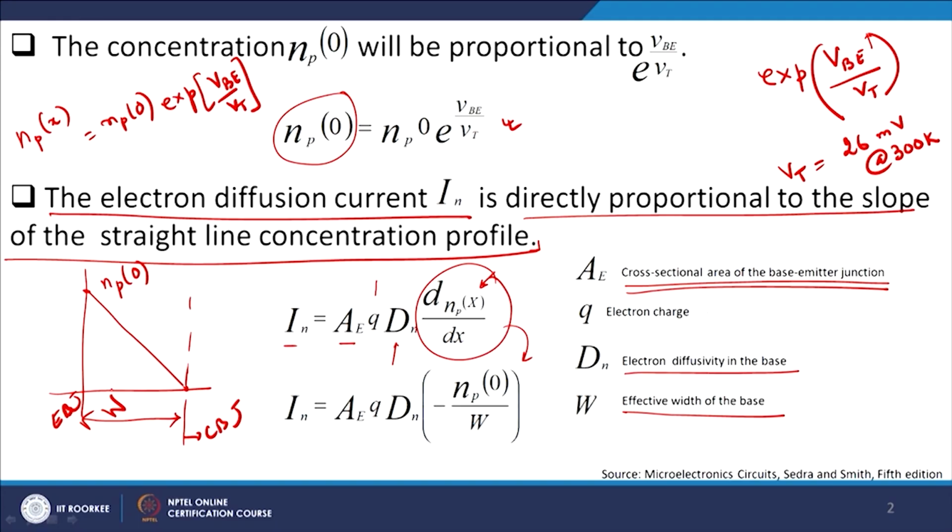Please understand one more important point here, that in no way does the depletion width on the emitter base or the collector base junction influence your electron concentration in the base region, the minority carrier contribution, because they will nonetheless be available at those particular points, and therefore it will not affect the overall concentration of the minority profile in this case, right.